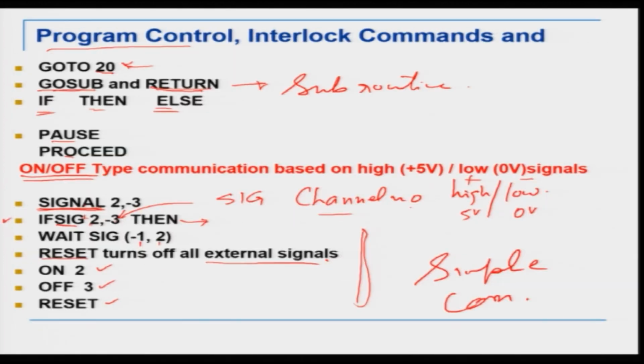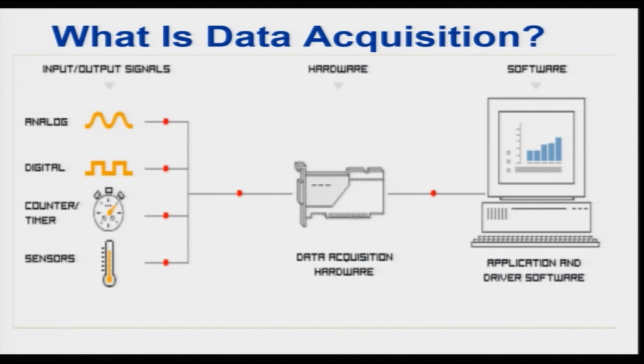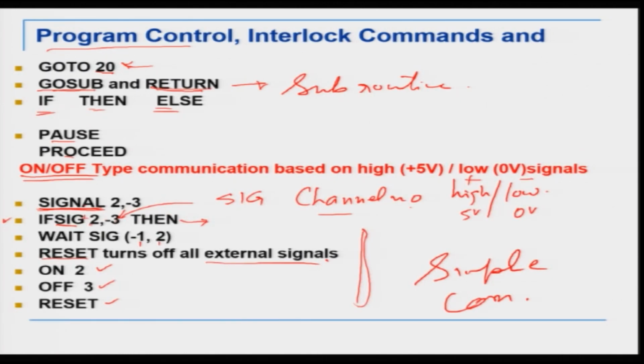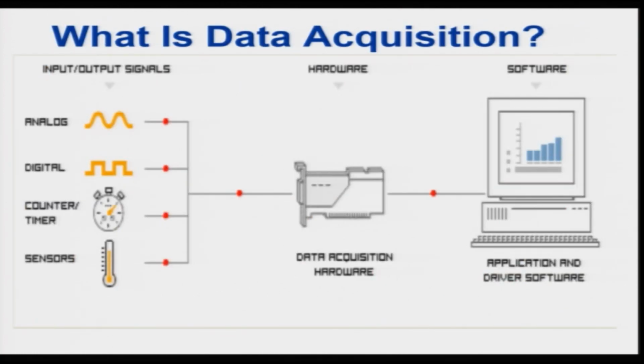Now, if you are using other sensors, for example force sensors or torque sensors, or light curtains or lasers measuring some distance, then this information is not essentially high and low. That is continuous information, and this continuous information essentially comes from analog signals. So, this is my analog signal. Let us say force, distance, then torque.